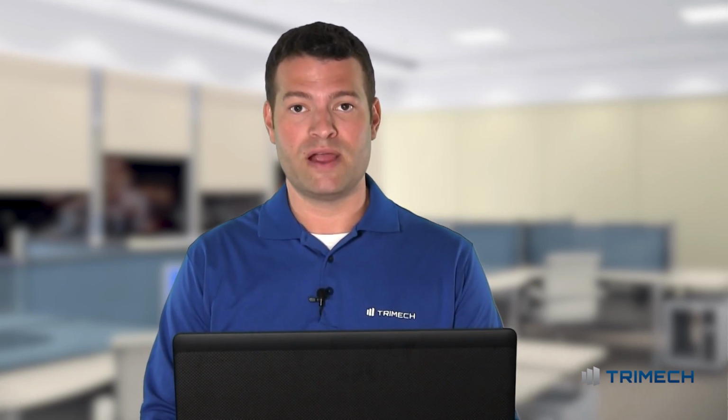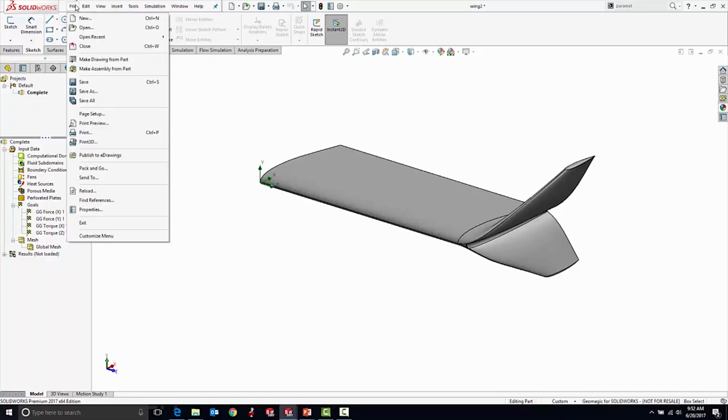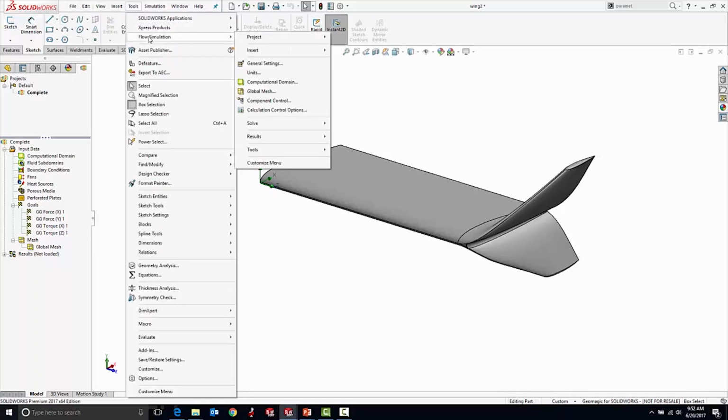I want to check for both the lift and drag that it's going to produce on the aircraft, and I also want to look at the torque that the flow applies to the wing to see if the attachment point that I'm going to design is going to be strong enough, if it's going to rip the wing off of the aircraft, right? So again, I'm going to start this off in the flow simulation wizard.